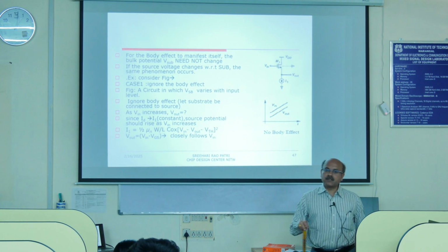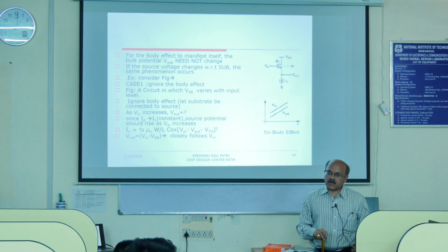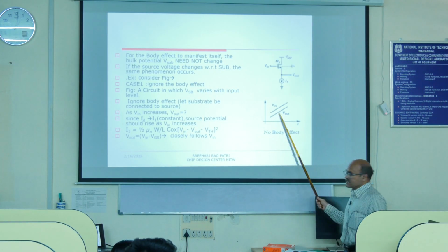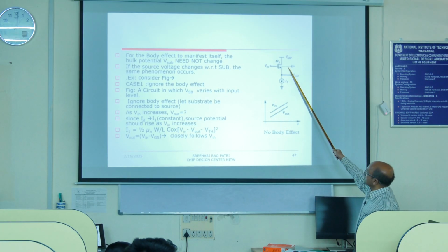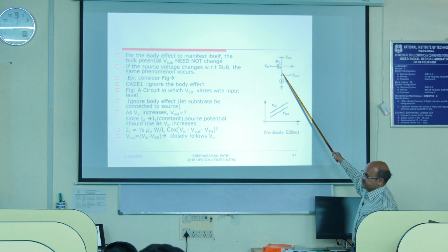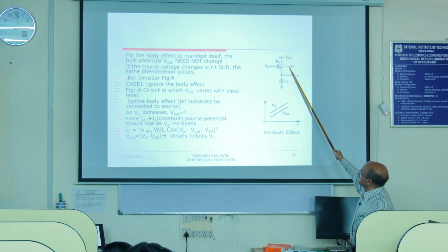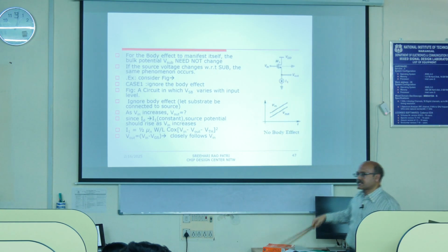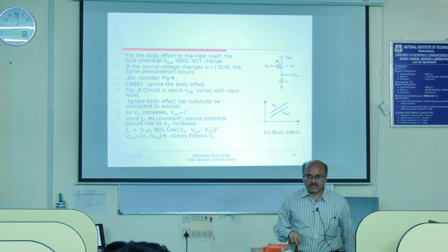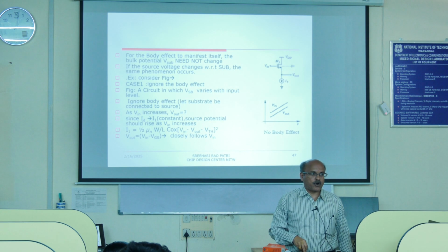Threshold voltage, right? So above threshold voltage only it conducts, right? So therefore this is what is a source follower. Now whatever the connection we thought, we have removed it. Then what happens? This is the source, the bulk is at ground, source is not at ground. Therefore the circuit experiences body bias effect. Am I right? Circuit experiences body bias effect.